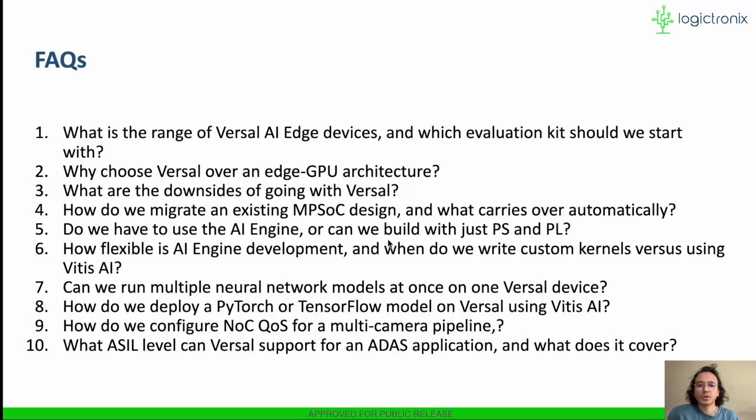Also, if you have use cases or workloads where it is not a standard operation, you have signal processing stages mixed with inferencing, and you need direct or complete control over the tile level data flow, then custom AI engine kernel creation is recommended. In our own ADAS system, we have written custom proprietary kernels for all the LiDAR pre-processing pipelines before the data is fed to the NPU in the AI engine.